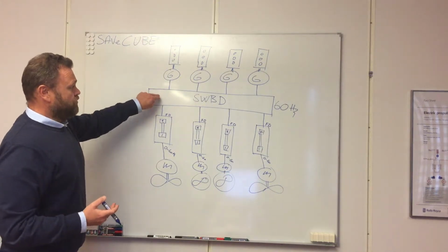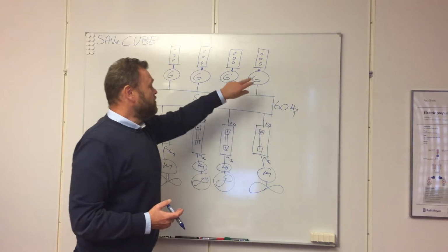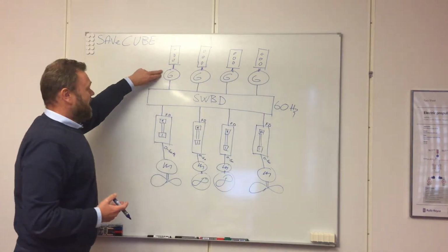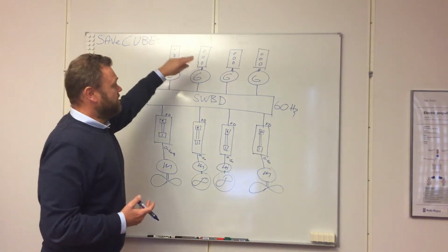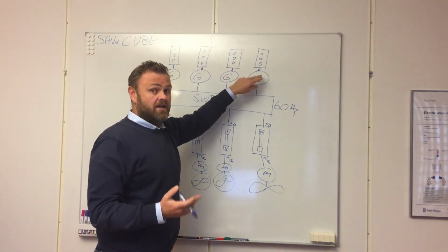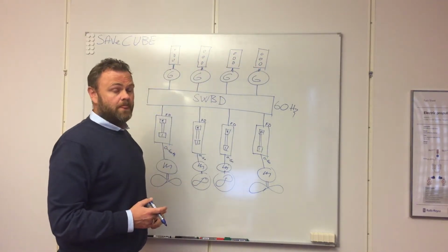And to be able to have 60 Hertz stable on the switchboard, you need to have stable RPM on all the generators, and of course on all the engines.